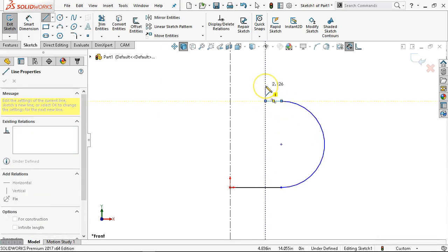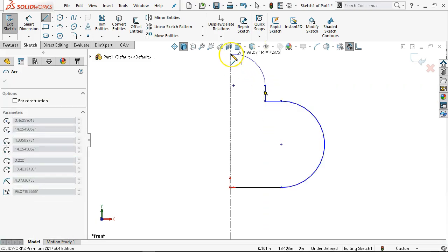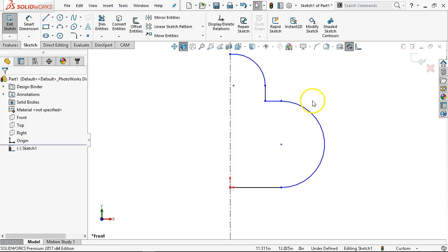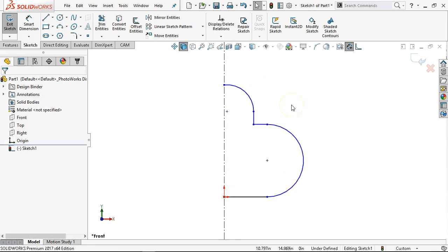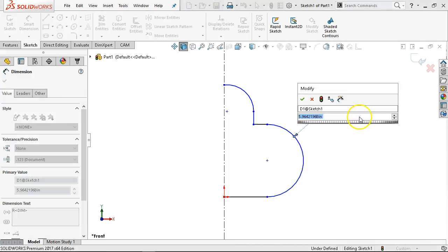All right, small line, another arc, back to the start point. And because this is symmetry, if I draw the whole arc, I'm going to mirror at least part of it back on itself. All right, so I'm going to put in a few dimensions to get the scale. And we had a 1.5 inch radius.